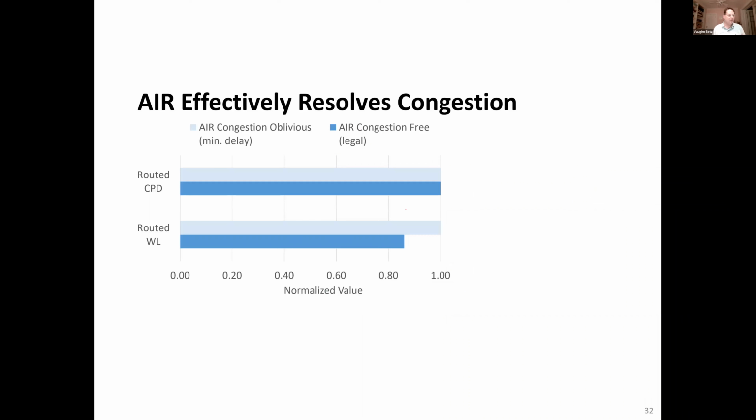And another thing that you can check with a negotiated congestion router is, what did it cost me to resolve congestion? So when we go from the initial routing, where we pay no attention to congestion, we're just trying to see what's the fastest we could connect everything, the minimum critical path delay. That's illegal. But that light blue line is how large would the critical path delay be if we were actually allowed to have congestion. And we find that when we resolve congestion, on average, we don't really move that critical path delay across that suite of Titan benchmarks.